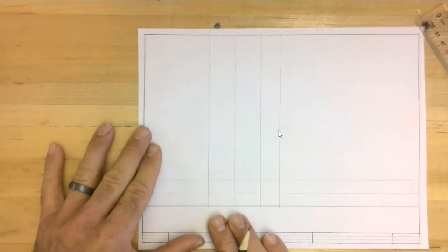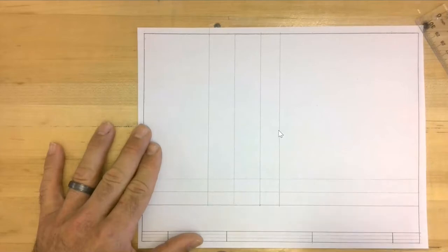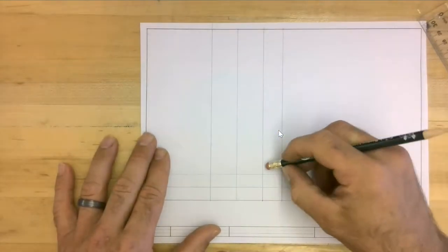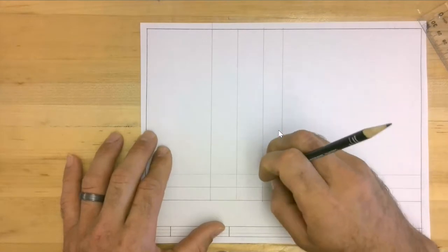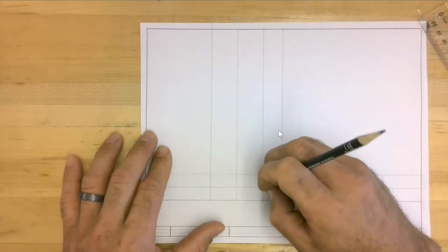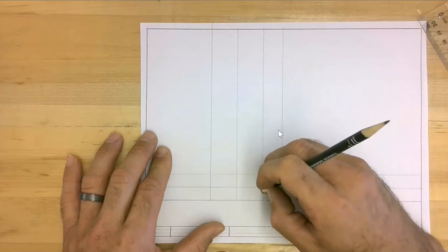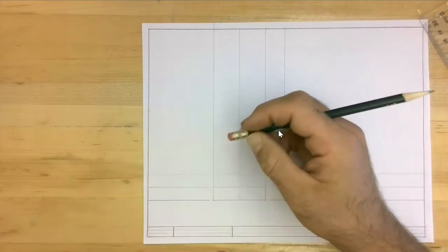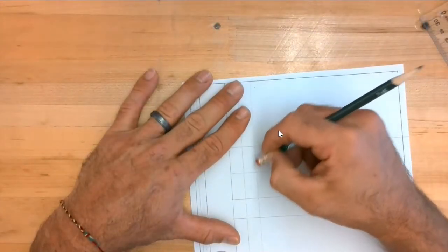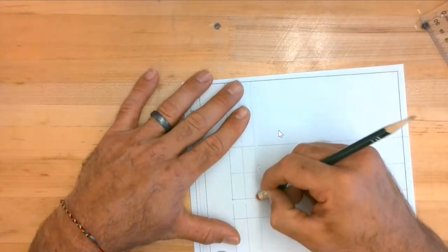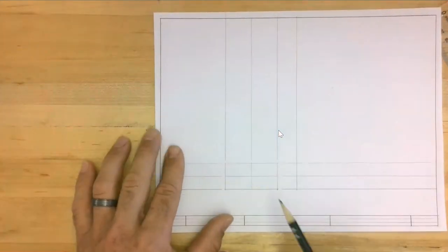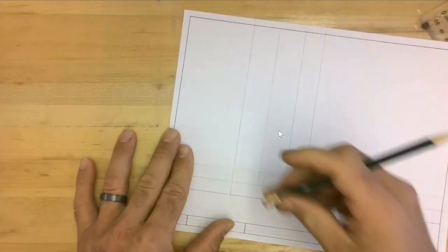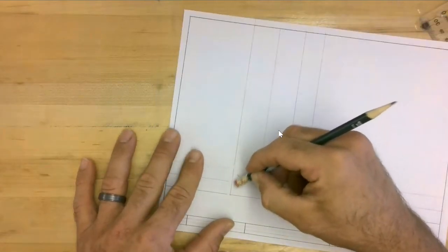And now my front view is finished, even though it looks a little cluttered. So at this point, because I've been drawing dark, I'm going to do a little bit of erasing to clean this up. When you do your drawing, if you draw lightly, then at this point, all you would do is come back and darken the lines that you would like to keep. So I'm going to just create a little separation around the outside to make this easier to see for you guys. And then inside, our cutout is in the top right corner. So I need to keep this line, and I can erase the other 2.